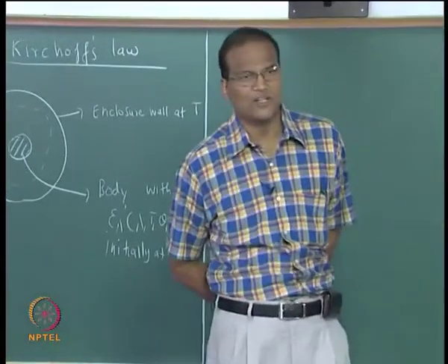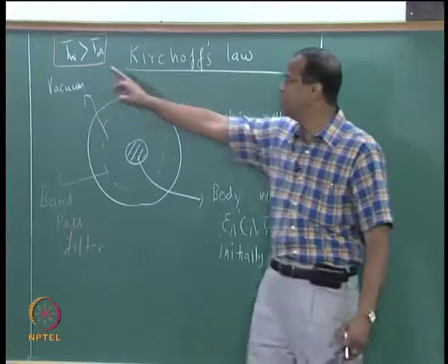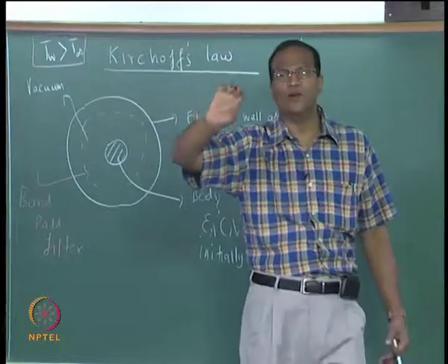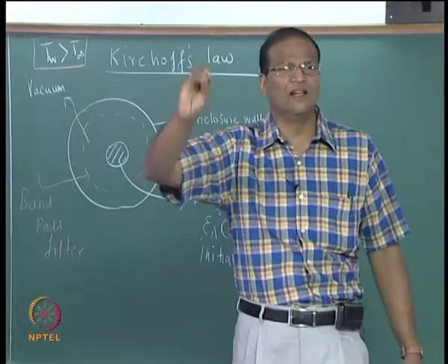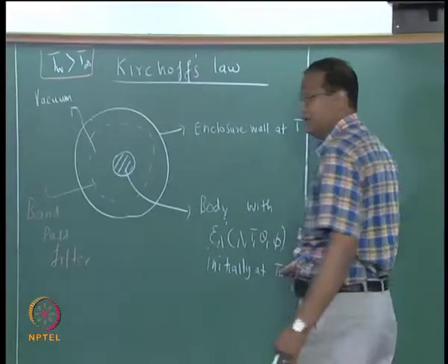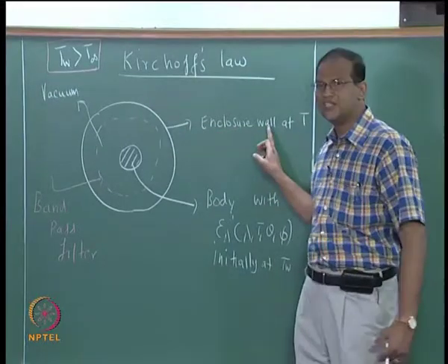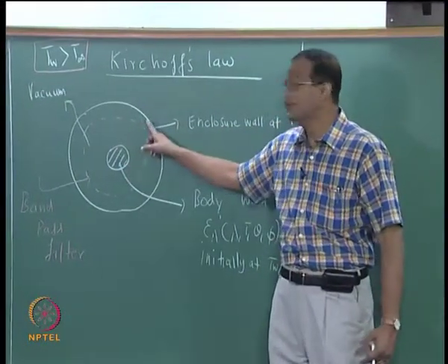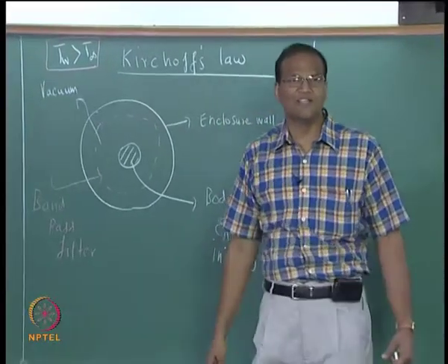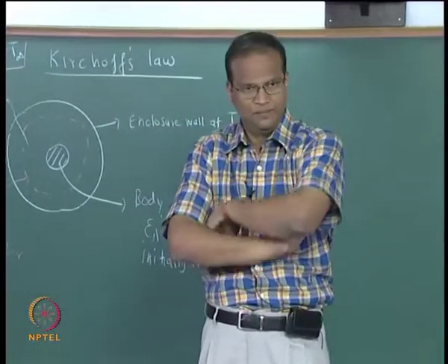Up to this it is clear, so it is not a black body. Now initially this body was heated, Tw is greater than T infinity. Now we allow it to cool. After a sufficiently long interval of time has elapsed, this body will also come to T infinity. Because of the transfer of heat, this ambient temperature will not change, because this is a small body in a large enclosure, which is capable of withstanding any amount of radiation coming onto it. That is like our sink, the ambient.